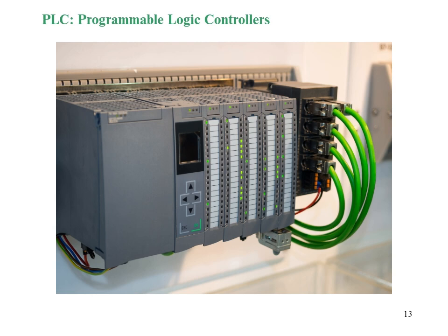This is a PLC. PLC stands for Programmable Logic Controllers. It's not a microcontroller, rather a PLC. The meaning of PLC is that it has a CPU inside, and also memory, output modules, and input modules. What it has inside is actually lots of relays. Relays are nothing but switches. If you go back to our fundamental theory, any logic you can implement using switches. That's important to know.